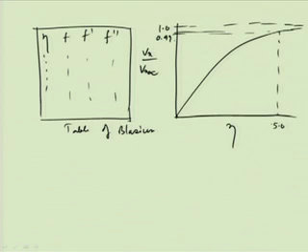So, according to his plot of Vx by V infinity versus eta, and also in the table, the same value is given. This is nothing but f dash. So, for eta equal to 5.0, its value of f dash is 0.9915. So, according to the numerical solution and the data provided by Blasius, we can say that